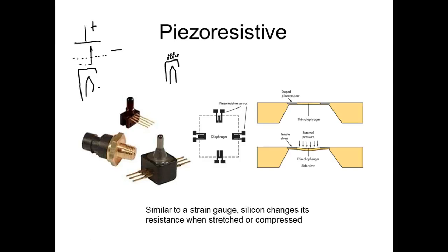But what they found out, guys, is that we could take silicon and we could put pressure on silicon, and silicon, there's a lot of semiconductors that vary its resistance with what? Pressure. So we could take these, and they operate similar to strain gauges, but strain gauges have to be warped. And they're really precise. These guys, you can just take them and press them like this, and then they'll change their resistance. So you can take these guys and just change.